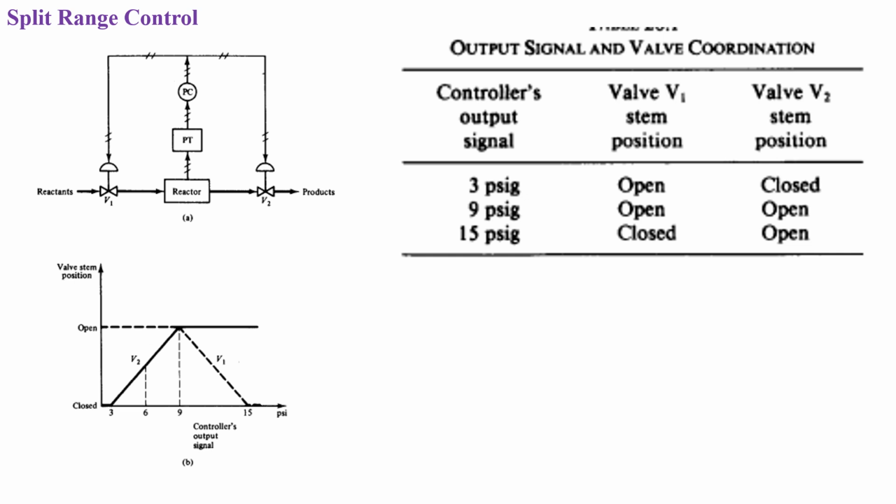So these are the takeaway points. Always the dynamics of the secondary loop must be faster so that the primary can achieve its target. So that's all about the cascade controller. So cascade is a multi-loop. In this, instead of one measurement, we have two measurements to achieve control within a short period of time.